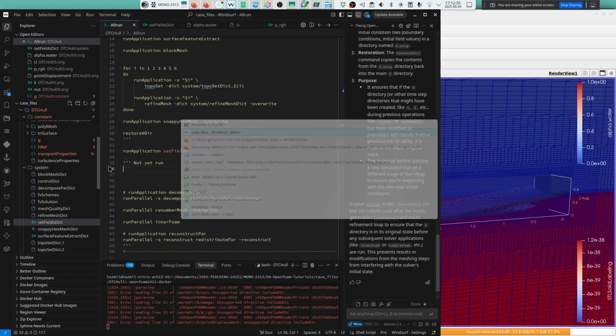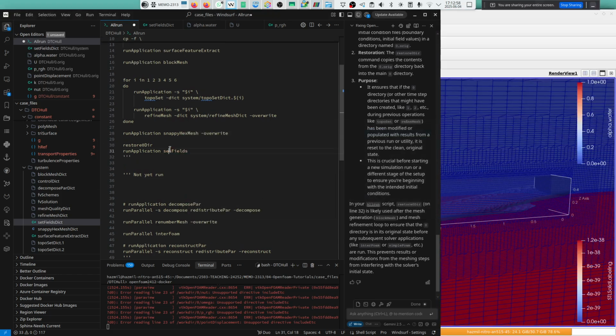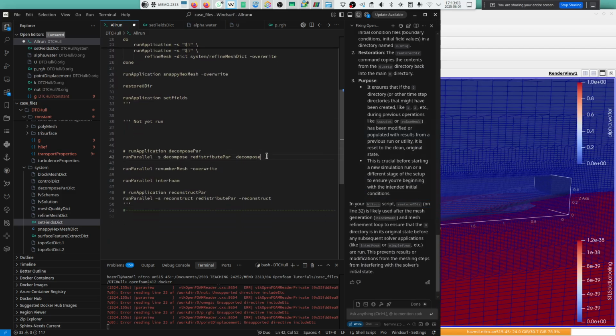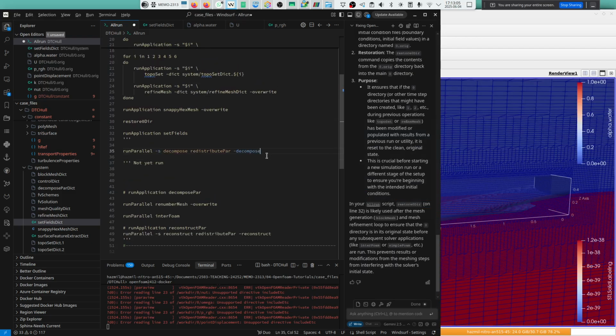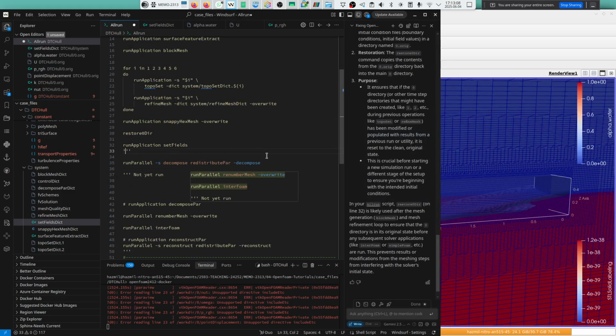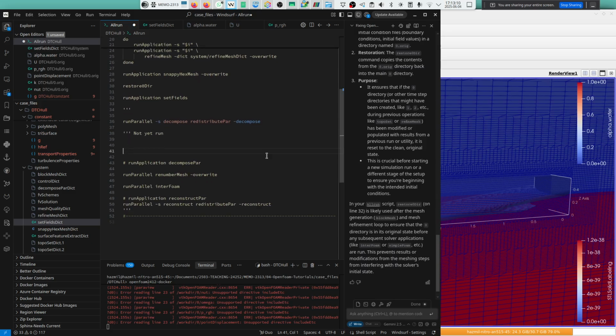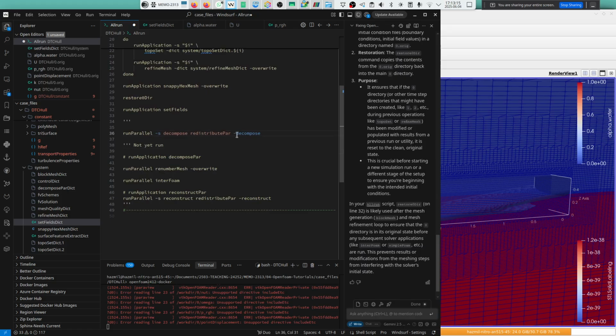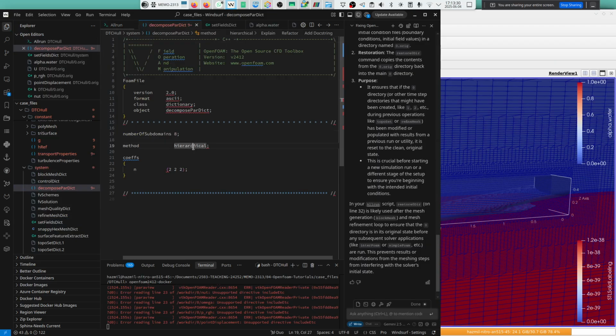Next, after you set the initial field for the water region, before we run it, we want to make use of our processors. Let's say my laptop has 8 cores, so I can change it to 8 cores. So before we run this, we have to specify decomposeParDict.